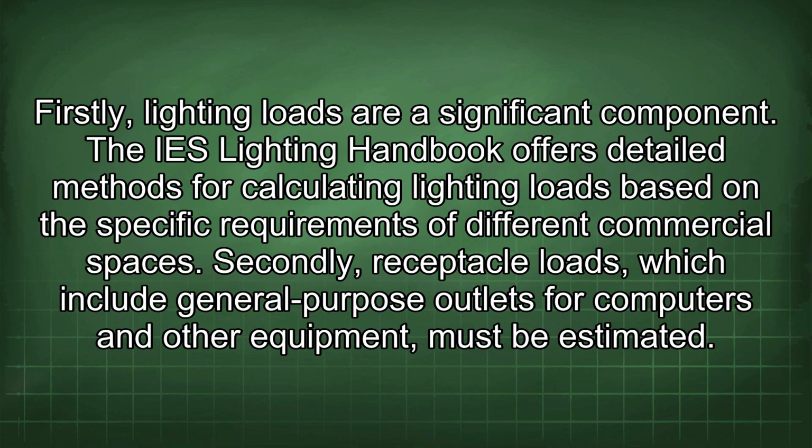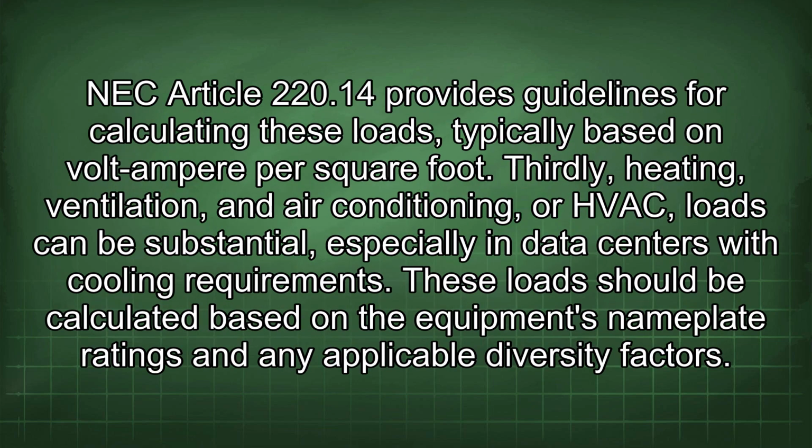Firstly, lighting loads are a significant component. The IES Lighting Handbook offers detailed methods for calculating lighting loads based on the specific requirements of different commercial spaces. Secondly, receptacle loads, which include general-purpose outlets for computers and other equipment, must be estimated. NEC Article 220.14 provides guidelines for calculating these loads, typically based on volt-ampere per square foot.